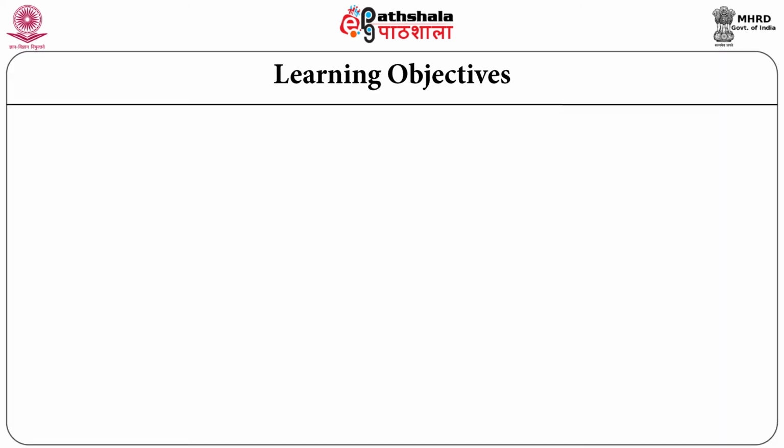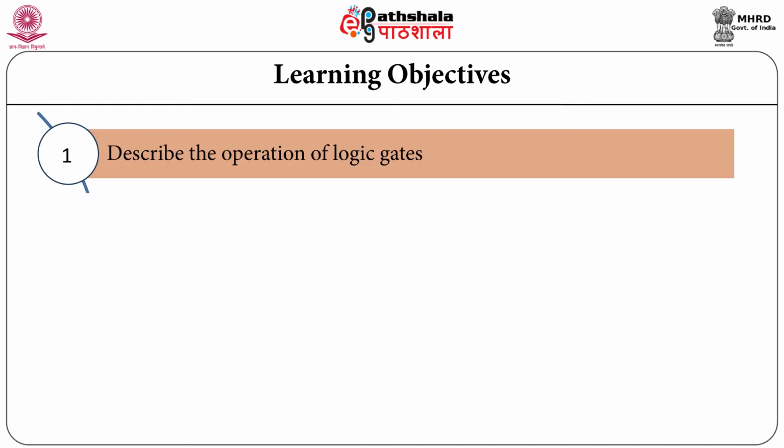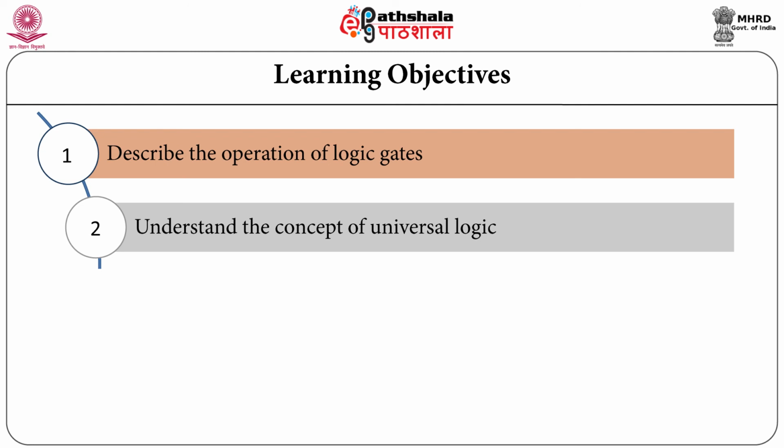In this module, you will learn about the basics of logic gates and why they are referred to as the fundamental building block of any digital system. The operation of logic gates will be explored using analogy and truth table. In addition, you will understand the concept of universal logic gates, how NAND and NOR gates can be used in constructing other basic logic gates.